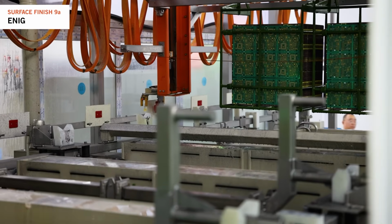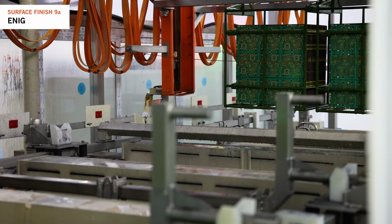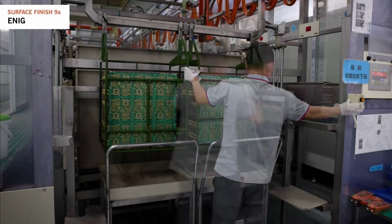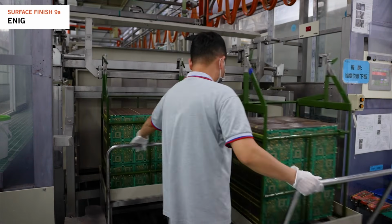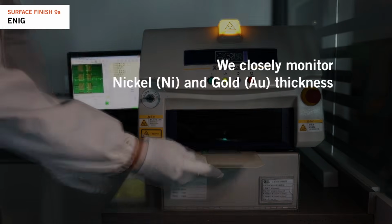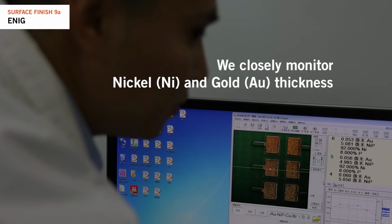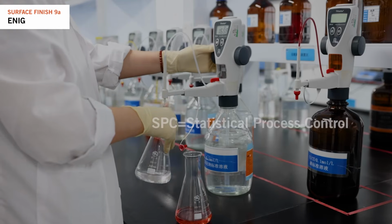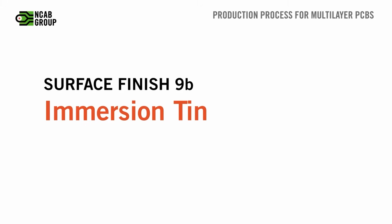NCAB has dedicated quality staff in the factory to oversee the ENIG line, ensuring it functions correctly and conducting tests for superior quality, particularly in solderability. We closely monitor nickel and gold thickness records and check all chemistry parameters. Given the complexity of the process, maintaining good SPC is crucial.